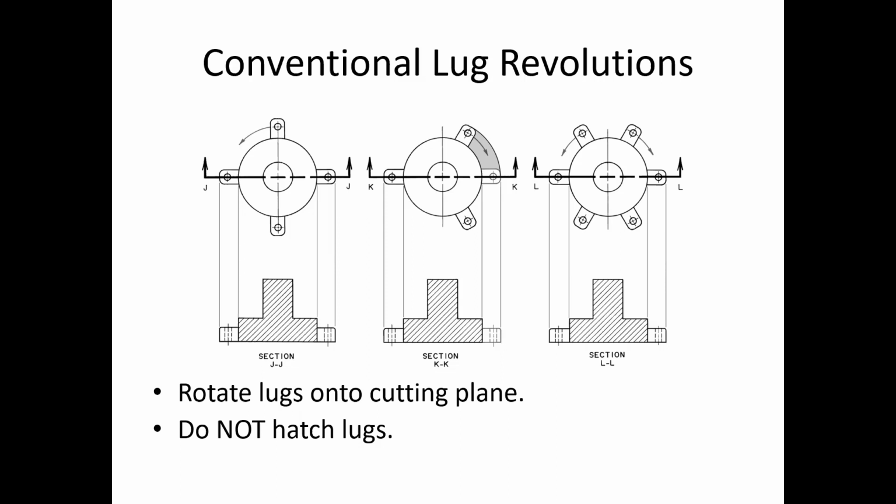It's making me think a lot that these cutting lines never go through these features. Oh, you've been taught wrong all along. Well, yeah, maybe we should start explaining it like that. This cutting line is really not going through that. You just project it like normal, right? It's too much work to make this cutting line go up here, like they have in some other sections. They've just decided to not make it go around the feature.